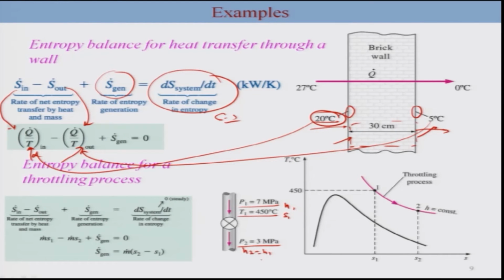So based on that you can find out S2 from the table. Okay, now you can look at this entropy balance here. This is assumed to be adiabatic, so there is no contribution due to the heat transfer. The contribution is mainly due to the mass flow. So this can be written as m dot (s1 minus s2), because m dot is fixed considering a single stream steady flow